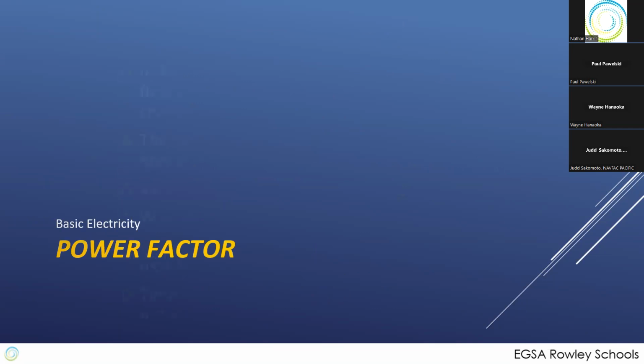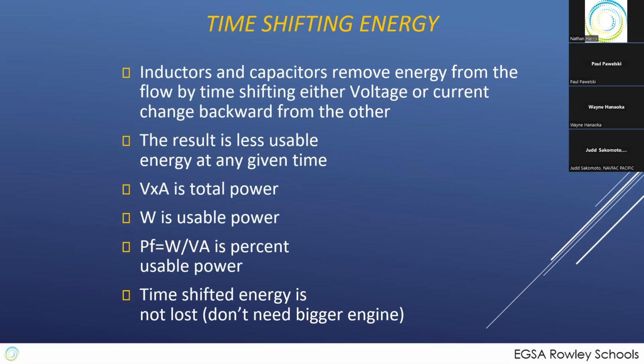And that brings us to power factor. And I really hate the foam and beer analogy because it's not really making sense. V times A would be the total power. Remember that if we had just actual resistance, voltage would never cross the zero point except when amperage does also, and so we would always get the maximum amount of power that's possible. But since we do offset because of inductors and capacitors, there is a usable power, the amount that we actually get if we added up instantaneously all of these points. And the difference between those two is power factor.